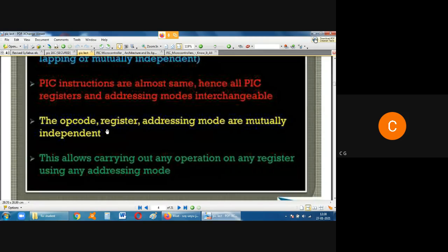For the microprocessor to do this operation, what you have to do is 3E. 3E is the code to move immediately the data. Then it will ask for the number, so from the keyboard you have to give the data. 3E is MVI A, meaning you immediately move something into register A, from the small keyboard available.